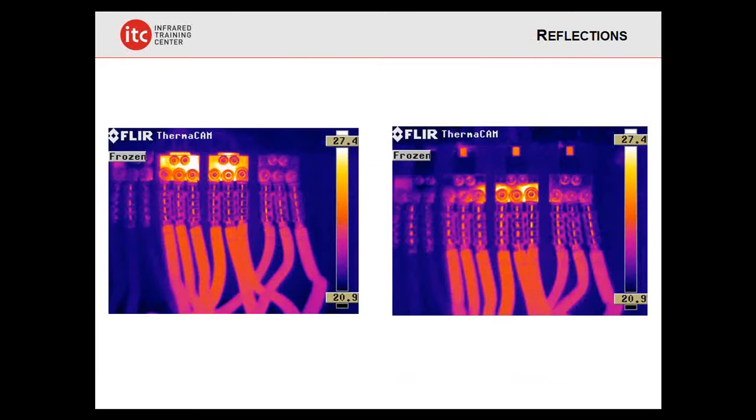And that's a really great point that you lead to there, Gary: if you see something that appears to be hot and you're not sure if it is, move. Good thermographers are always on the move, changing their position. And if the hot spot moves, what you're seeing is likely a reflection. That's illustrated here on the left as we're looking at this connection, very perpendicular. On the right, we've now moved and the reflection moves. That's one way of identifying false positives in this situation.